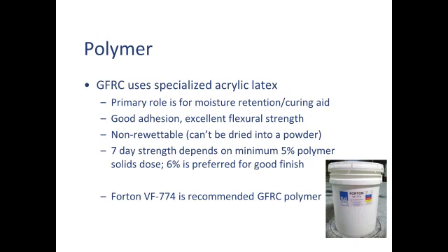There are actually international specs for it. And these all say 5 to 6 to 7% polymer solids for wet cure. If you choose to use something else and use less polymer, you're going to have to wet cure your concrete for the full 7 days to get that 7-day wet strength, which is why you use polymer in the first place, so you don't have to do that.